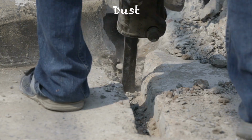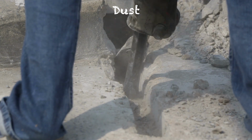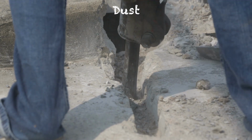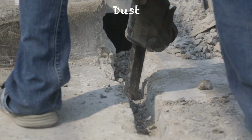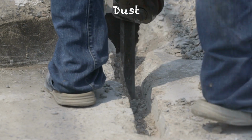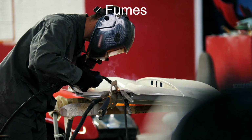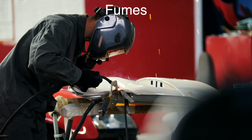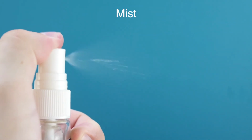Dust are solid particles. They are generated when handling powdered materials or pulverizing larger solids. One notable example of dust is respirable crystalline silica. Long-term exposure to this type of dust can lead to a serious lung condition known as silicosis. Fumes are vaporized solids that have recondensed. Metal particles that have become airborne during welding fit this classification. Mists are liquid droplets that have become aerosols.